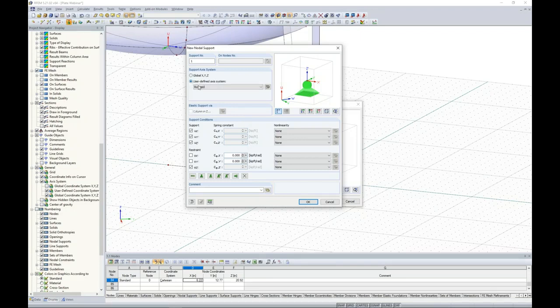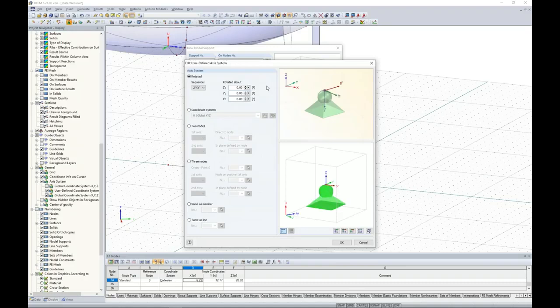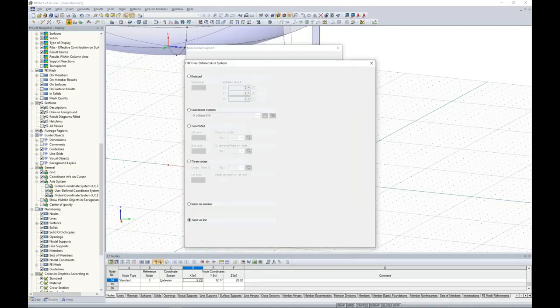Well, we can use this option here to rotate the axis system. And I go under my detail settings here, and I can specify the specific angle about the X, Y, and Z axis I'd like to rotate, but better yet, we have the ability down here at the bottom to reference another object in the model. And for this example today, I can graphically select this line.